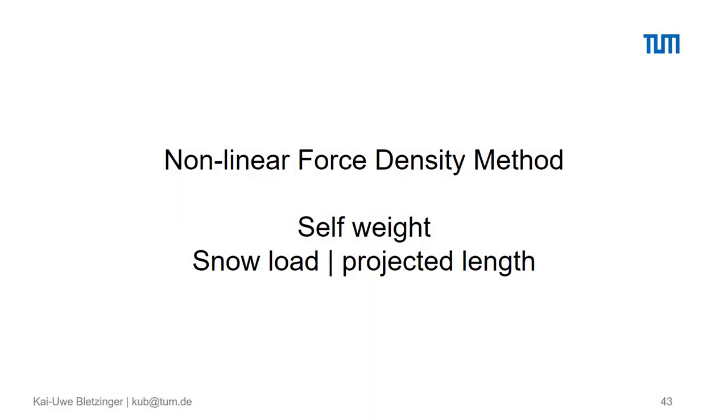We now come to self-weight and snow load. Snow can be considered with respect to the projected length of the cable, and we will see in a moment that these two load conditions generate non-conservative mechanical problems, which in particular will lead to non-symmetric stiffness matrices.